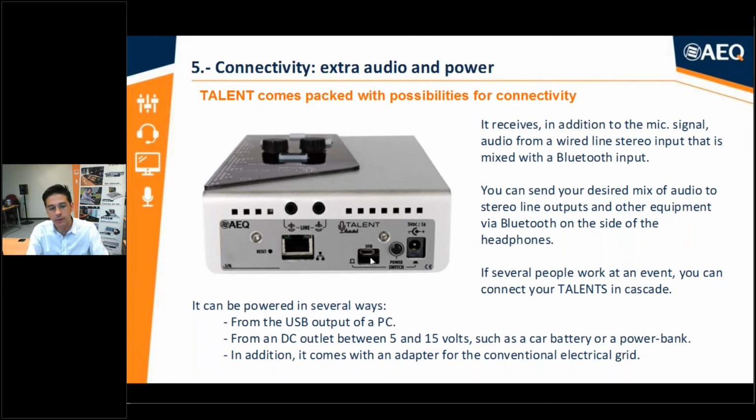Okay, so it accepts 5 volts here. And here there is an additional power connector to connect the provided AC/DC adapter. We provide one with each unit, and as opposed to what is written in this label, it accepts from 5 to 15 volts. So it can also be powered by a car battery, for example, if you have the proper cable.